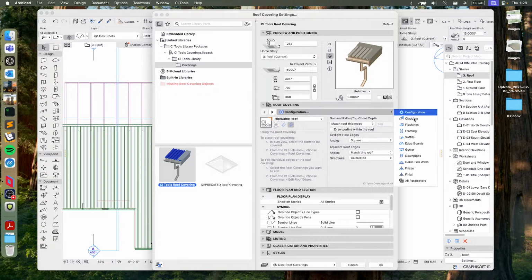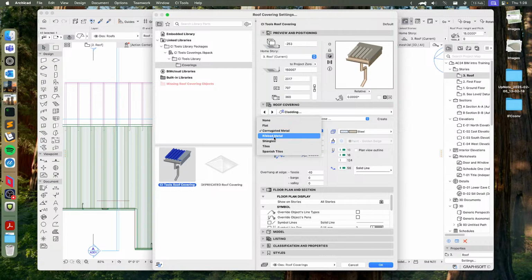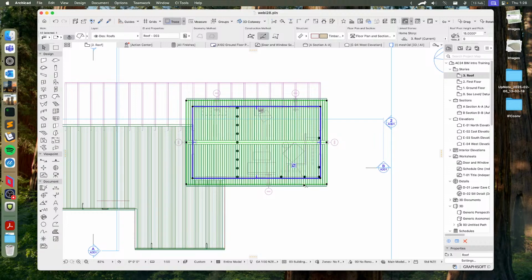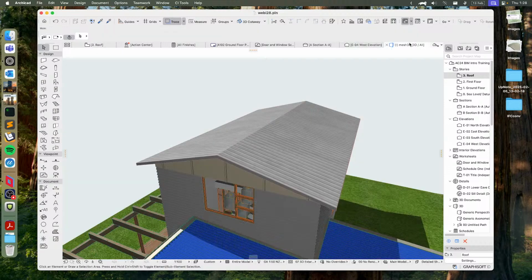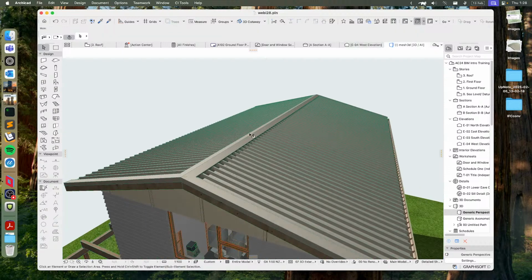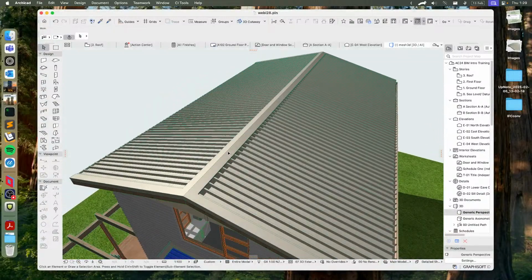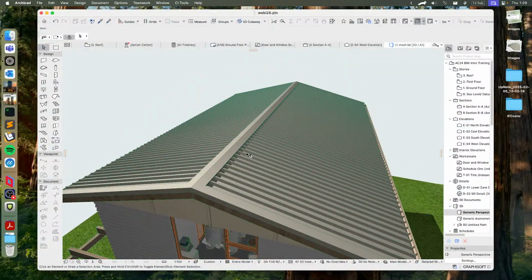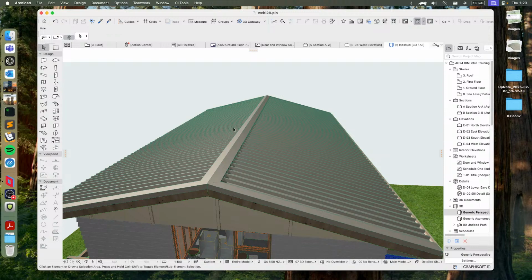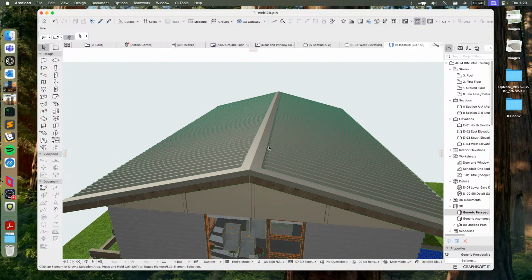And we are going to apply a ribbed profile to this. Hit OK. That places our cladding on, and we can see that we've got our rib profile here. What I want to do is get the ribs to just miter essentially directly across, so that there's no big chunk of flashing in the middle here.